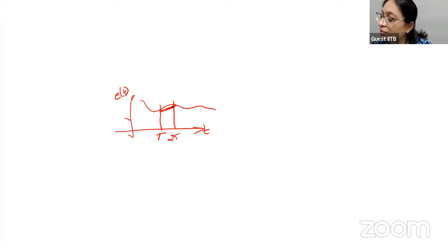So this difference is going to be fine if the signal is this kind of very nice wavy signal. But typically the measurements are corrupted with high frequency noise. And this high frequency noise gives you trouble always when you do the differentiation.